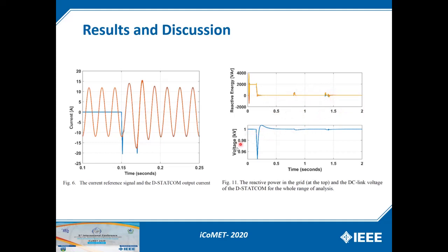And we can see here the DC link voltage in kilovolts, and we see that it is controlled for a long time. So the voltage controller is also well verified. Just one comment: here it is written reactive energy because the conservative power theory defines the reactive power as reactive energy, but the concepts are quite similar. Reactive energy means reactive power in a broad concept of electrical systems.